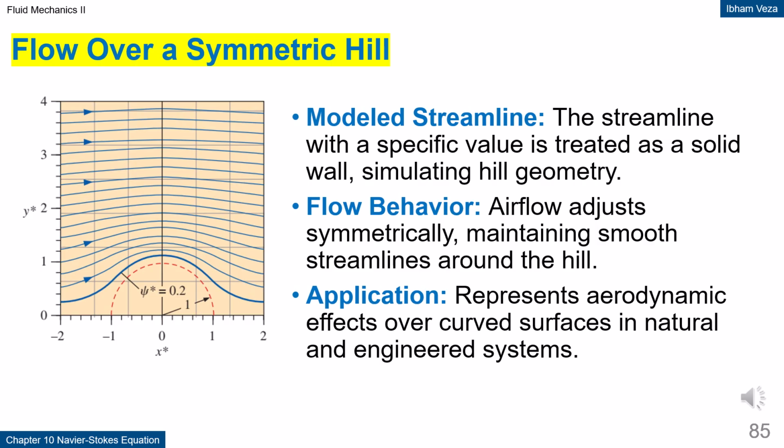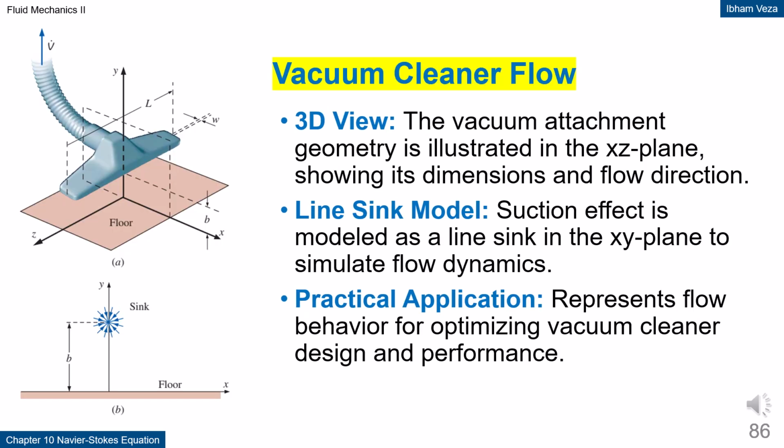Although idealized, this model provides initial insight into terrain aerodynamics. It also shows the flexibility of potential flow methods in modeling complex geometries. Vacuum cleaner flow. The flow in a vacuum cleaner can be modeled using the line sink concept.